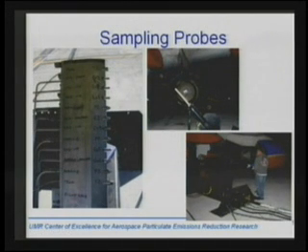In particular, the particle probes need diluent to be introduced right at the probe tip. This is done to control the relative humidity in the sample, to minimize agglomeration processes, and to basically turn off any subsequent reactions that might occur in the sampling lines.